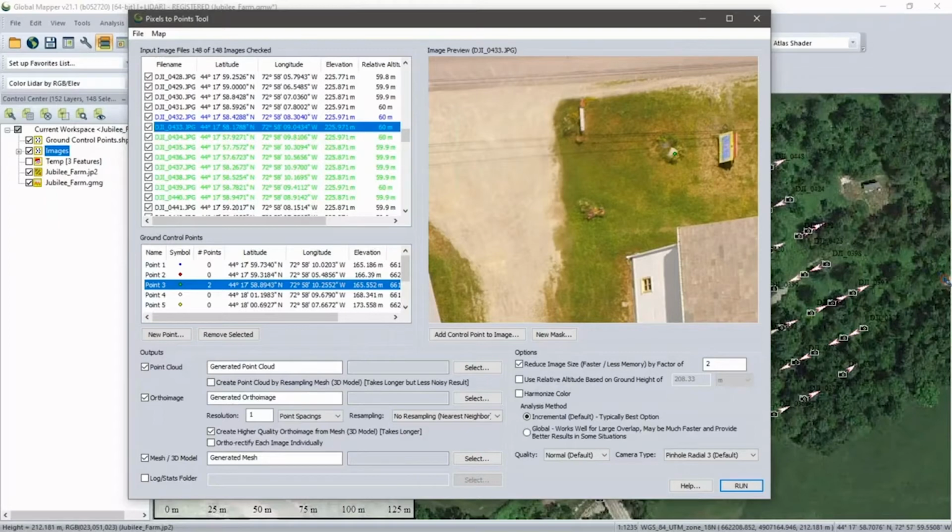That'll work very well. In situations like that, when you're dealing with oblique imagery, it's quite likely you're going to get content off on the horizon that's not relevant, and that's going to slow down the process and create data that's not necessary. Think of the situation where your oblique images are looking 45 degrees: you're going to probably get sky view in the distance, or at least distant horizon objects. We now have a tool for addressing that. We can remove the pixels, or the areas of our image, that we don't want Global Mapper to process, and that's through adding a mask.